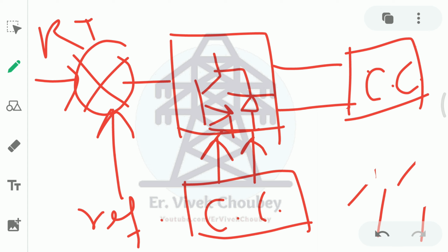So this is how the inverter AC works. As you can see that initially what we were doing, we were just seeing that if there is a temperature difference, yes or no. Based on that, there was just a binary selection, that is either the compressor will run or it will not run. Okay, but now what is happening? We are saying that what is the actual amount of temperature difference, and based on the difference of the temperature, we are driving the induction motor of the compressor.